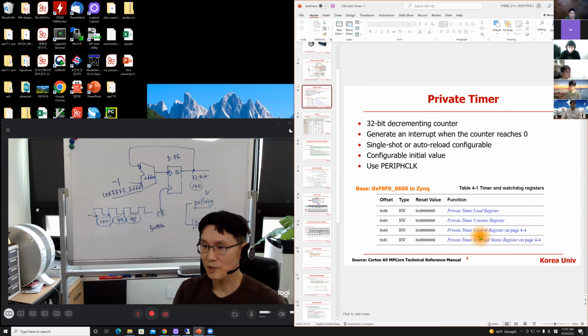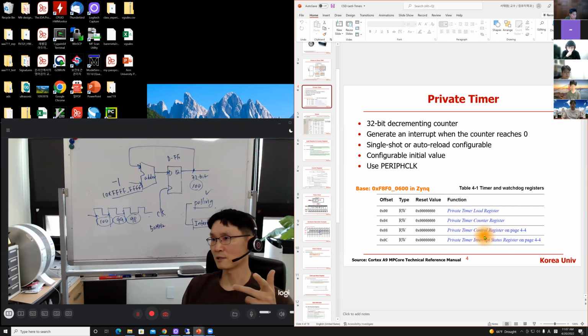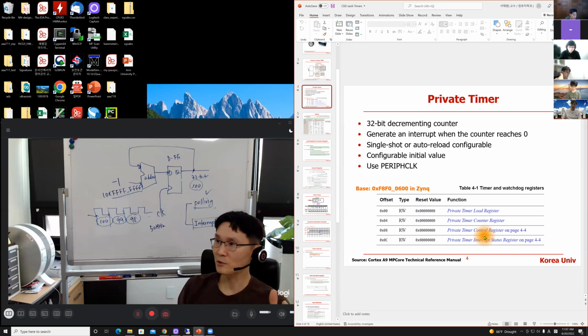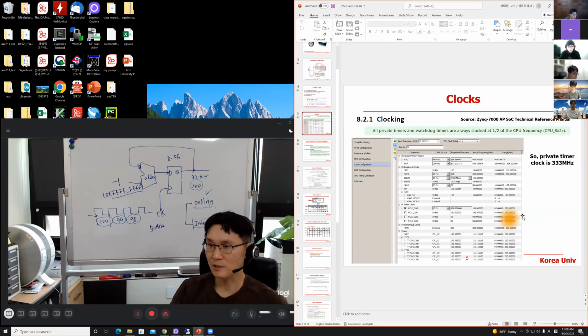What you have to do is you set control register. That is configuration register. Remember, 3 kinds of registers in IO device, in any IO device, right? The first one, configuration register. Before normal operation, set configuration. Second, data register, right? And status register. Control register is configuration register. Okay, and you have counter register and load register. Okay? Very simple. First, control register.